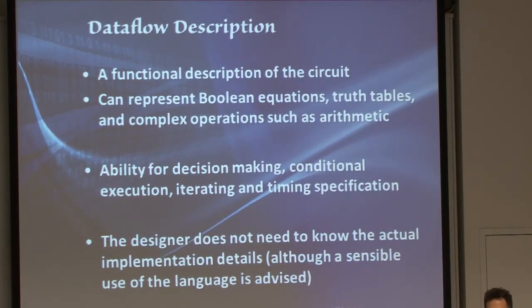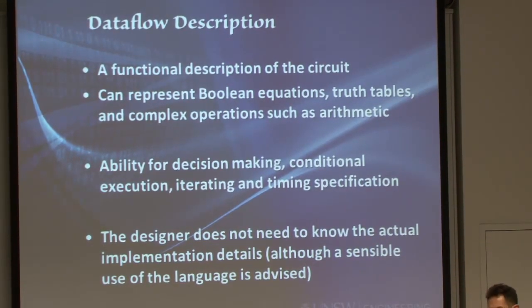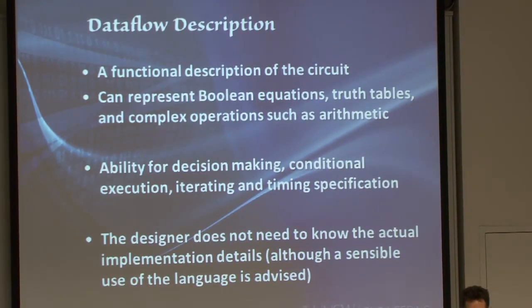The data flow description, also known as the behavioral description, is a functional description of the unit. You tell it what you want to do, so you can describe things like Boolean equations, truth tables, and even arithmetic. You don't actually have to build the circuits that do the arithmetic for you. And we will learn about arithmetic circuits in week 9, by the way. And then let Verilog or your CAD tools figure out how it's all implemented.